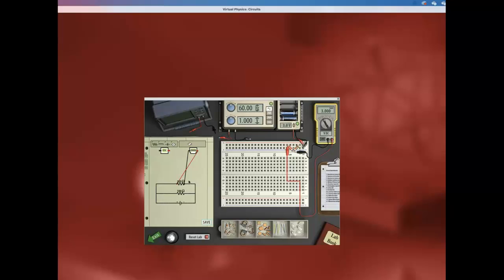Now for the parallel circuit, find the percent difference between current I, which is found in step 5C, and the answer found in calculation 1 of the parallel circuit, which was the addition of the 2 currents. And for the parallel circuit, find the percent difference between each of the 2 voltages measured in step 6 and the average value found in calculation 2 of the parallel circuit. Then here you are going to have 2 of them.